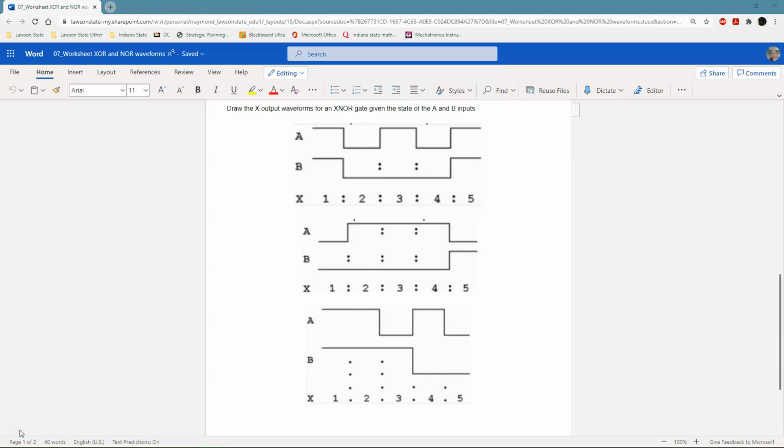All right. So if the exclusive OR gate is looking for differences, then the exclusive NOR gate is looking for similarities. In other words, if you remember, the truth table for this was that every time you have the same signal for both, you end up with an output. And every time your signal has differences, you end up with no output. Does that make sense?